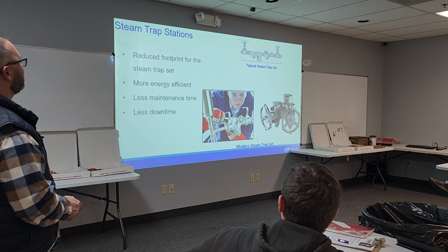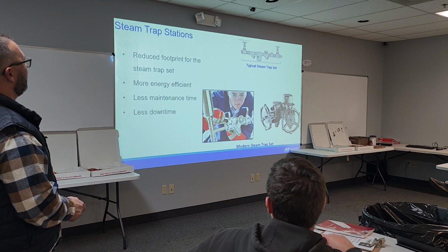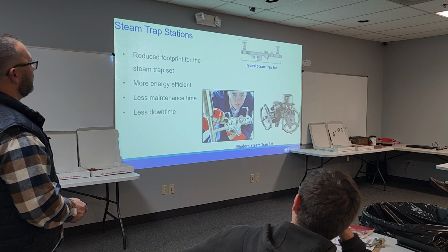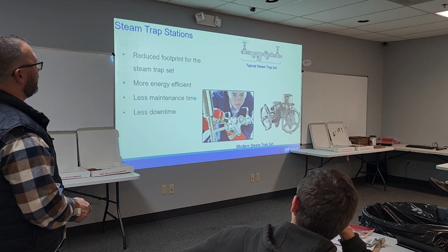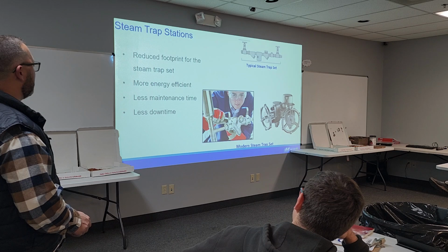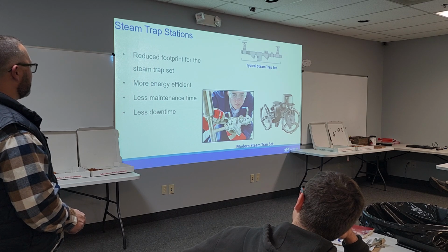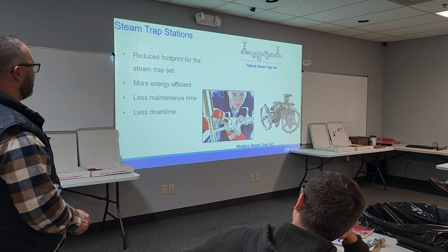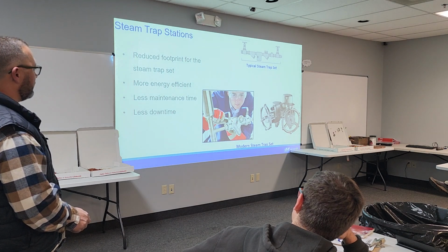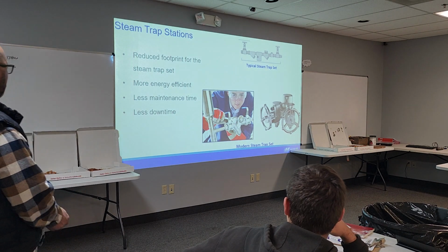We've got the gate valve, isolation valve. We've got the strainer. That's the Spirotech, loss detector. There's your trap. There's a check valve. You can put all that right in one small package. And again, when you're working in systems that you can't shut down, you got the isolation valves right there, 2 bolts, that trap comes off, bam, slap the other trap on it.